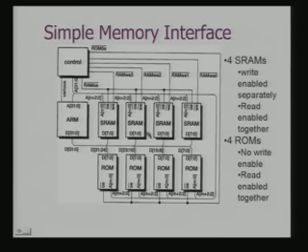So what we are saying is that they are read enabled together, but write enabled separately. Similarly, in the case of this ROM, no write enable signal is required because I do not need to write to them, and they should be read enabled together.